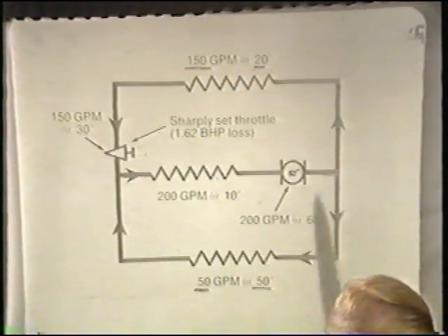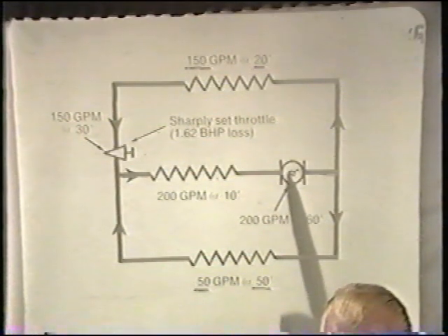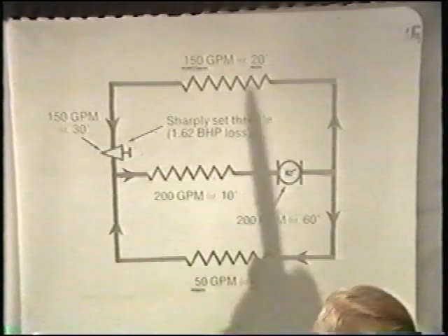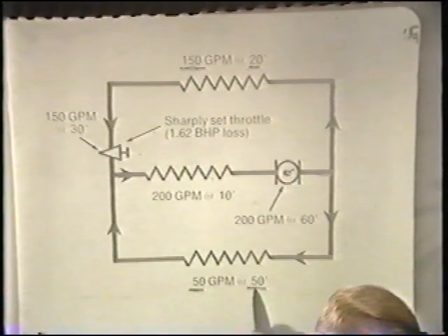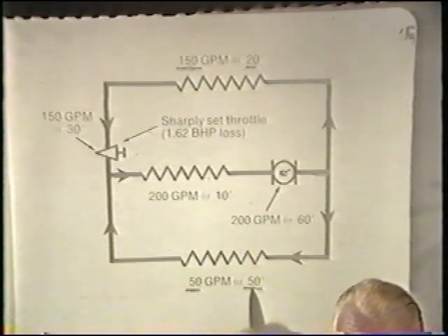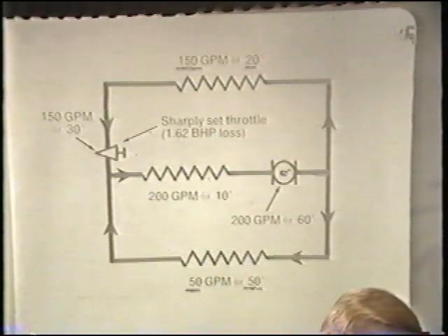This would then establish that the pump is basically sized in terms of flow by the high flow need, but in terms of head is selected in terms of the high head loss need for the high head loss circuit.